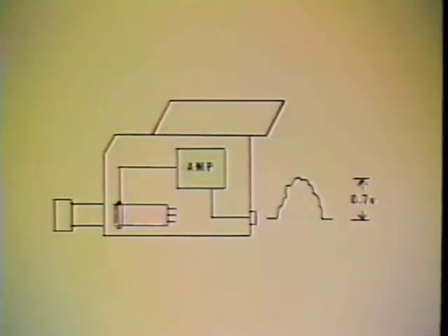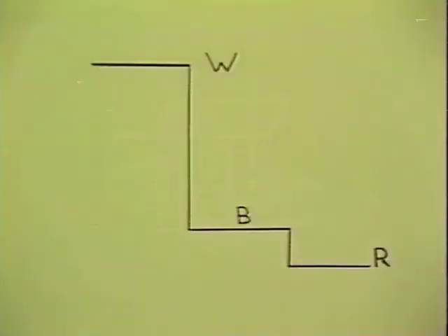This very low voltage is amplified to about 0.7 volts before it is sent from the camera to the monitor and other equipment. In this process it is inverted, so the blacks are represented by a low voltage, the whites are represented by a high voltage, and the retrace is represented by the lowest output voltage.